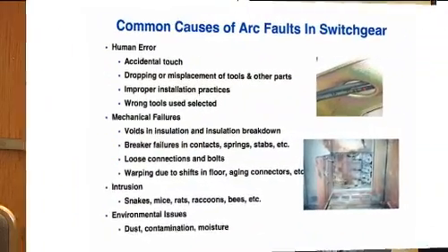It must be sealed, otherwise you don't have arc resistant switchgear. Many customers think that all they've got to do is train normal cables down into the cable way or cable pit and they're done. In arc resistant switchgear, you can't do that. You've got to put in gland seals on each of those cables to maintain the integrity of the cabinet itself.